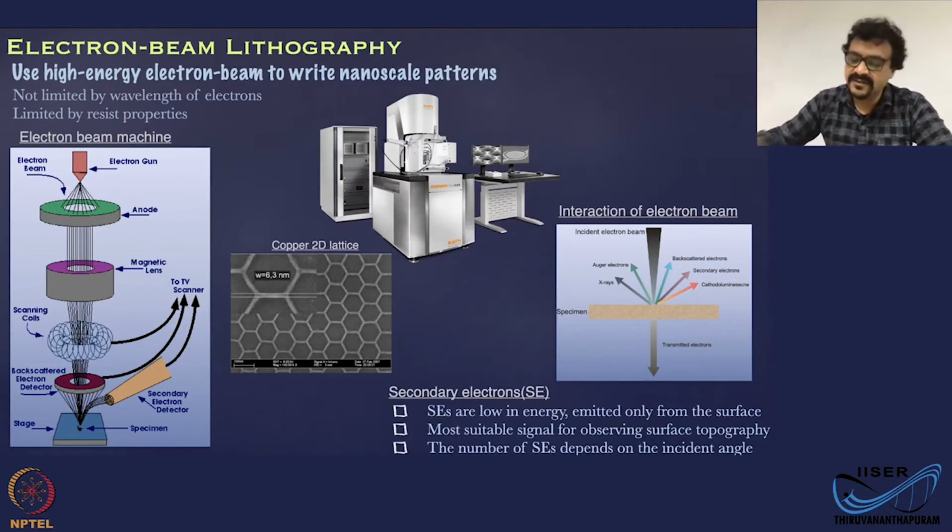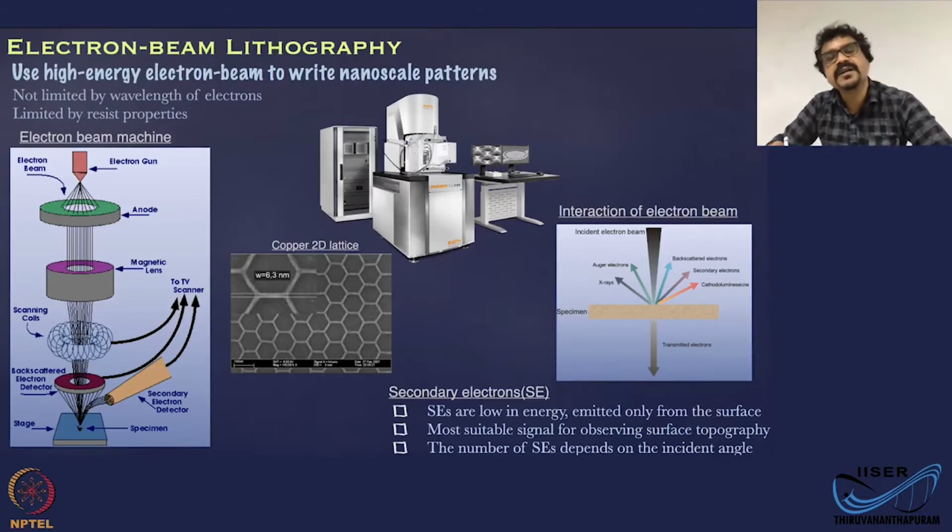In this case, what we are doing is we are using a high energy electron beam to write nanoscale patterns. So here we are not limited by the wavelength of the electrons. We are mostly limited by the resist properties and also the quality of the electron beam optics.